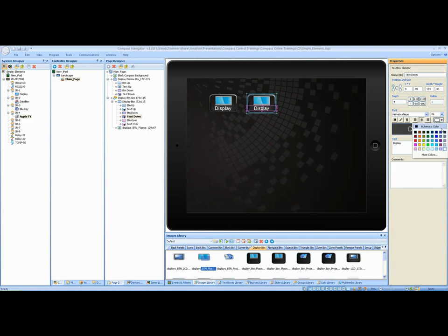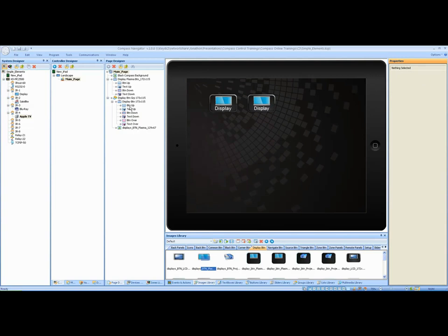So now you can see, in that down position, you know me, I like to go with that sky blue font coloring, and now we could take a look at this graphic. We could go in emulate mode here, Control E, and see what happens. It's up, it goes down, it pops back up, right? Why don't we see the over position? Well, recall that when you're just pressing a button, it goes up, it goes down. What we have to do here is actually tell it to go into that over position when it's pressed down.